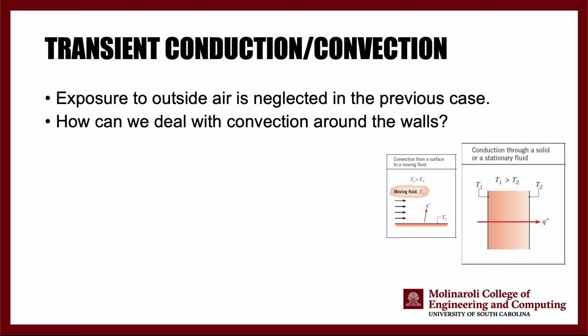When you have a heated copper block, you put it in air, you are going to see convection with the outside air. We are going to give you a fan. You're going to put that fan in front of a heated block and then another heated block without the fan, essentially simulating free and forced convection scenarios. And we are going to ask you to calculate how strong the convection heat removal is going to be.